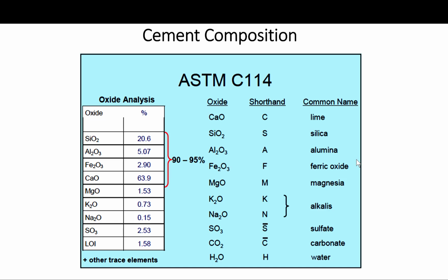This slide here shows the typical percentages of the major and minor components of the oxide analysis. It is important that the engineer is familiar with these elements and the specifications on his or her job, so that the mill certificate can be reviewed carefully to match the specifications and the requirements. Okay, it is very important to be able to read the mill certificate and flag any anomalies or anything that may not comply with the specifications written for your job.